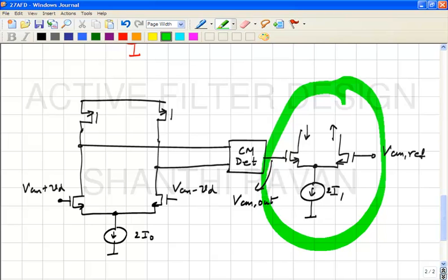Okay. So I mean, using the differential pair, I know that the current in one arm is I1 plus some GM times the differential voltage. Another one is I1 minus the differential voltage. I want to generate a single ended voltage. Please note that the output of this op amp is only one, is referred to ground, correct? So I need to generate a single ended voltage which is some large number times the difference between these two voltages. So what should I do?